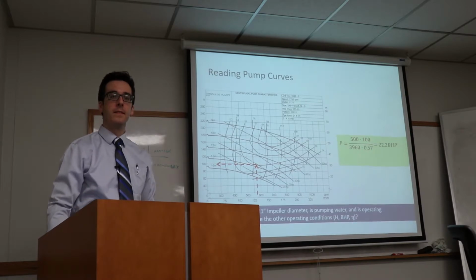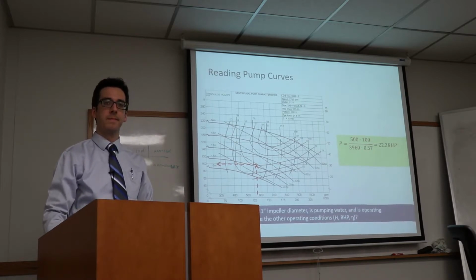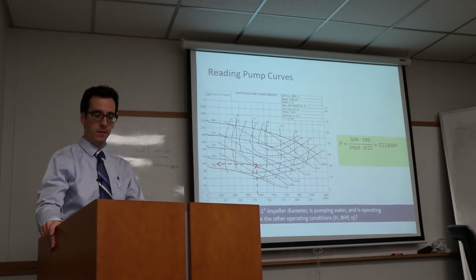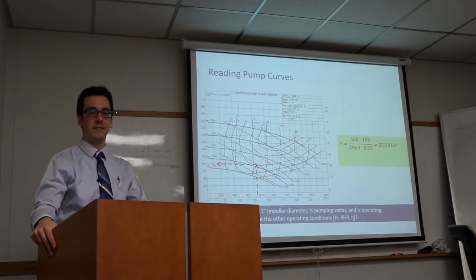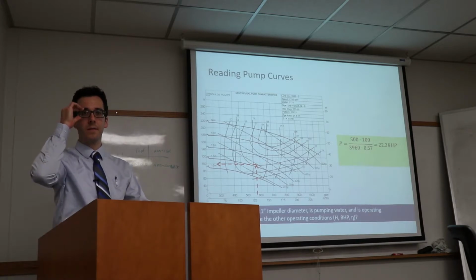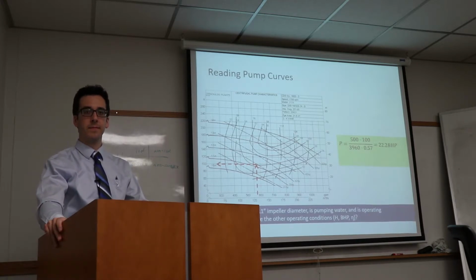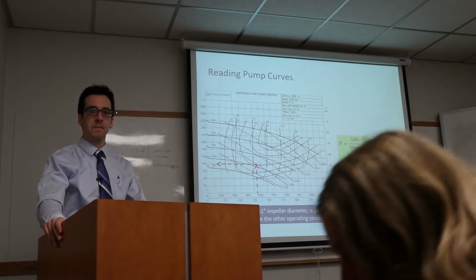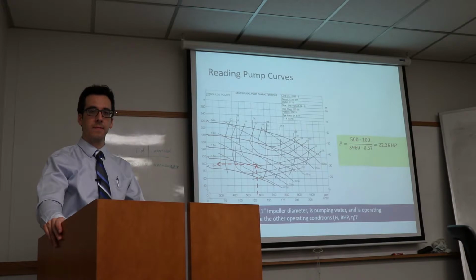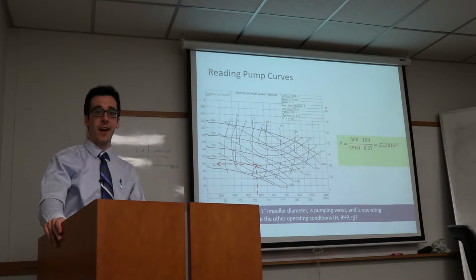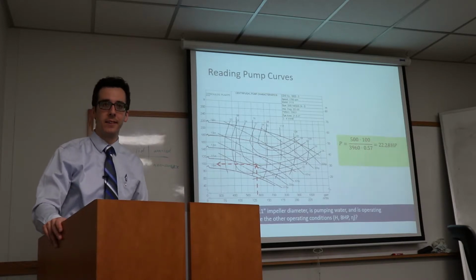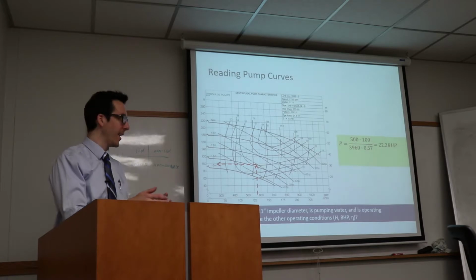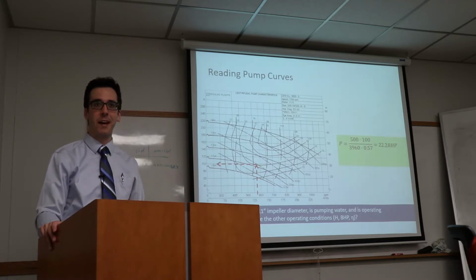Just a quick question. You have static head and you have head loss. I'm confused on this: if you have a pump that is designed for, let's say, 11 feet of head, or 100 feet of head, is it pumped to overcome that amount of pressure losses? Yes. Or is it usually above spec, or is it usually just at that? It's meant for that. So you design to the total dynamic head. Maybe you put some safety factor in there because you're not going to get it exactly right. You might need an 11 and 13/16 inch impeller to do that.